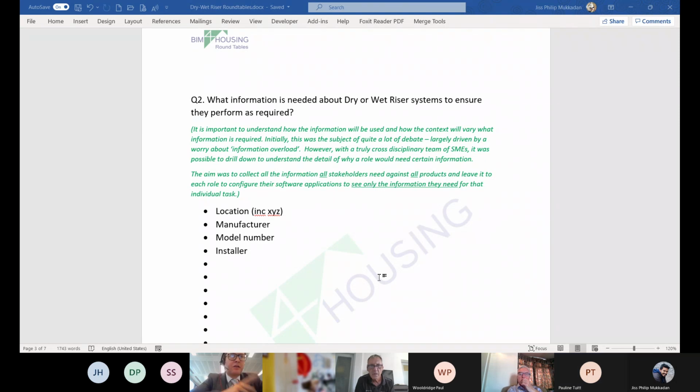Yeah, so I was going to say, I missed this bit earlier as well. Obviously they've got to be able to run for the duration of the fire. So time's an important one. Time for what? Time to expiry, or it's the same for sprinkler. The sprinklers should be sized for a certain amount of heads and a certain tank volume so that they can run for a certain period of time.